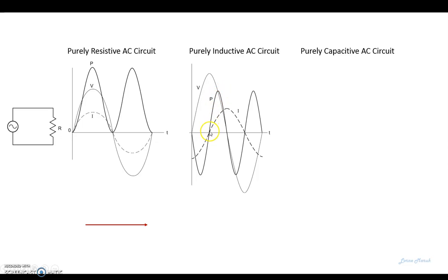In this case, it is not true power, although it's represented by a P. This is what we call wattless power, or VARs, also known as volt-amp reactive. And of course, when our voltage goes negative, we could have positive current, so we have negative VARs. So this isn't doing any work.